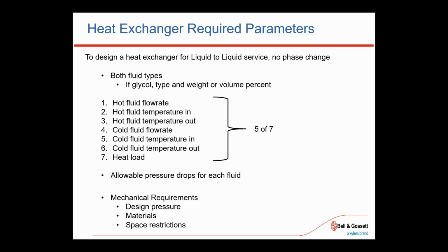So we made a slight adjustment to the approach temperature, which made it so that we could reduce our surface area and how tall the unit was, which reduced our frame size. There was one selection we had, but as these different variables got piled on, it became the third revision of it. But it's nice to have those details at the start when we can.